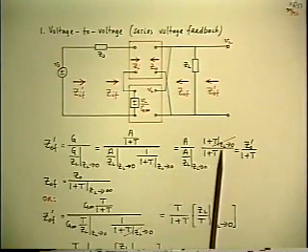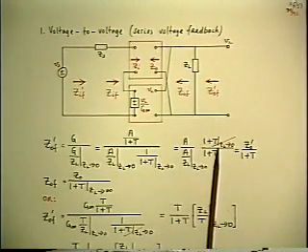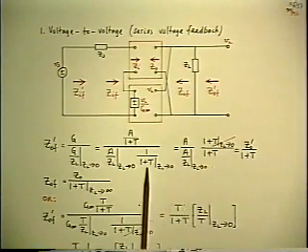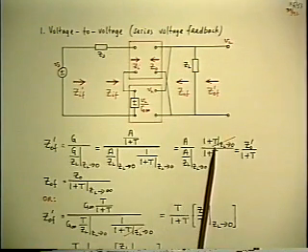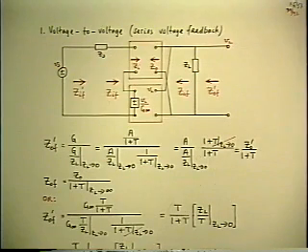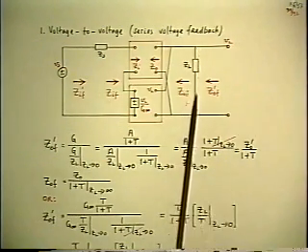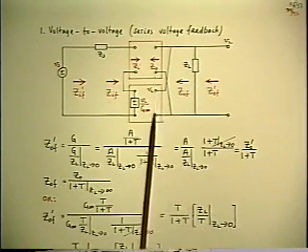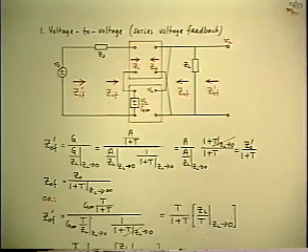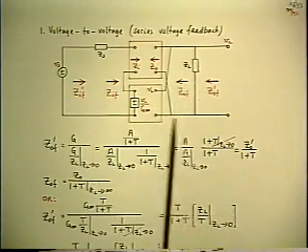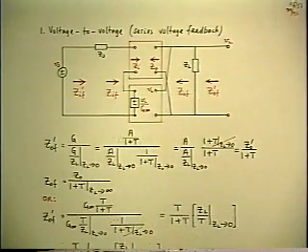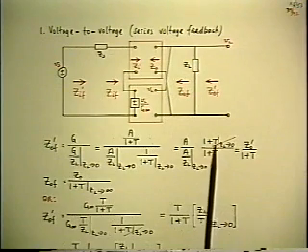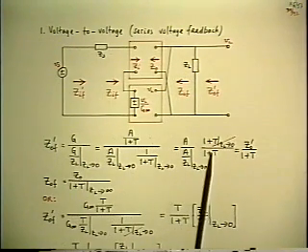So then you look at what's left. Well, here's T as ZL goes to 0. And that must be 0. Why? Because if you short the output, you kill the loop, because the feedback box is connected right across it. So if you short the output, there is no feedback. You've killed it. So T goes to 0. And you're left just with the 1.